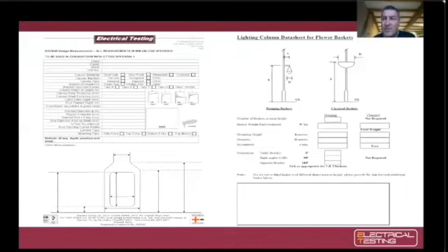So on the left, you have our data sheet we work with on site. On the right, you have the data sheet that we ask you to complete. So simply on the left-hand side, remember we've structurally tested the column, but now we're going to record the column material, we're going to record the column section, the column type, the bracket arrangement, we're going to record the column height. We need to measure the base thickness of the column, we need to measure the shaft thickness of the column, we need to know the cable entry hole depth, and we need to know the planted depth.